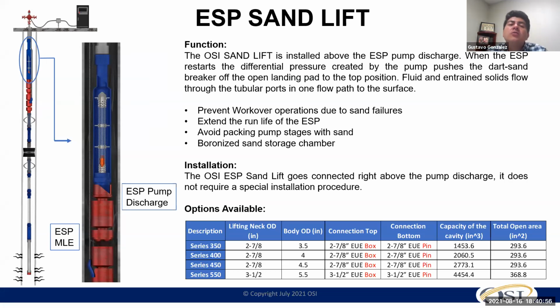The problem becomes when you're dealing with high sand volumes. Now you get 3-4 joints above the check valve, and your discharge pressure is not high enough to overcome that hydrostatic pressure plus the weight of sand above it, and you start pulling the well just because of that problem. So this particular product is able to regulate the amount of sand that is coming back.